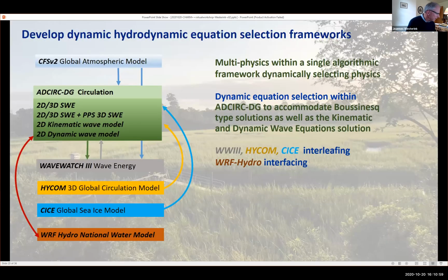So now the next step is really to pull in physics into the ADCIRC framework itself, not the coupled models that are running simultaneously, but within the core of ADCIRC. And the main thing that we're working on is to change the hydrologic components that couple in with larger scale hydrology, i.e. the rainfall runoff. And that is with these two sets of equations that are essentially simplifications of the shallow water equations that are typically run much cheaper and much better for the hydrology.